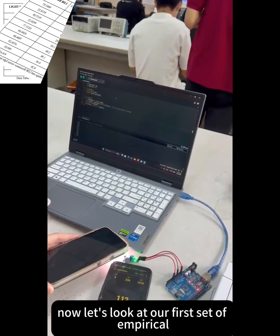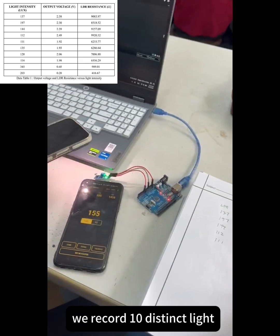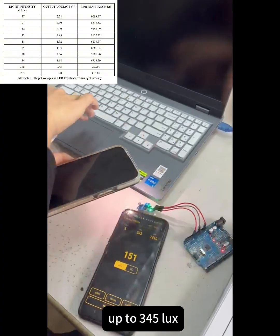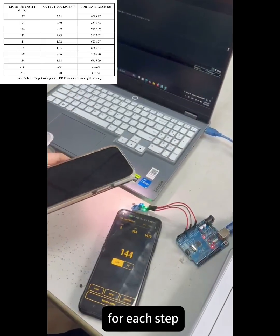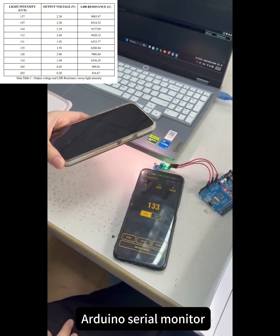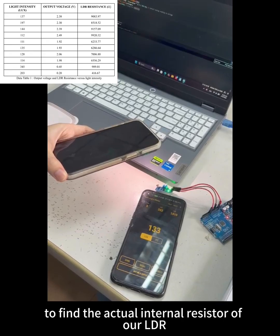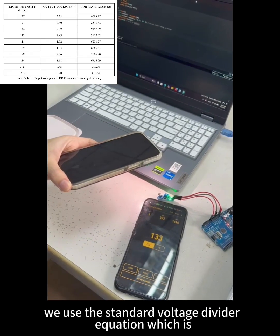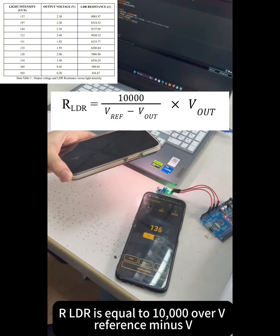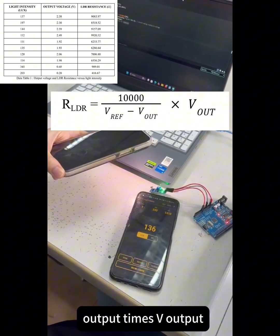Now let's look at our first set of empirical data shown here in data table 1. We recorded 10 distinct light intensities ranging from 111 lux up to 345 lux. For each step, we noted the output voltage directly from the Arduino serial monitor. To find the actual internal resistance of our LDR at each step, we use the standard voltage divider equation, which is R_LDR equals 10,000 over (V_reference minus V_output) times V_output.